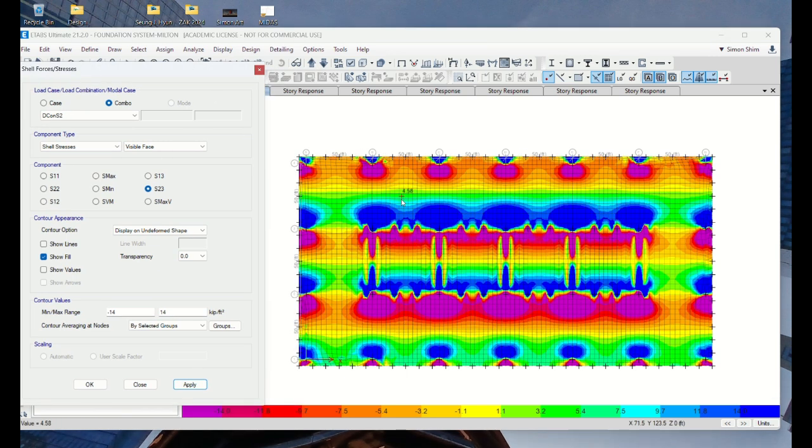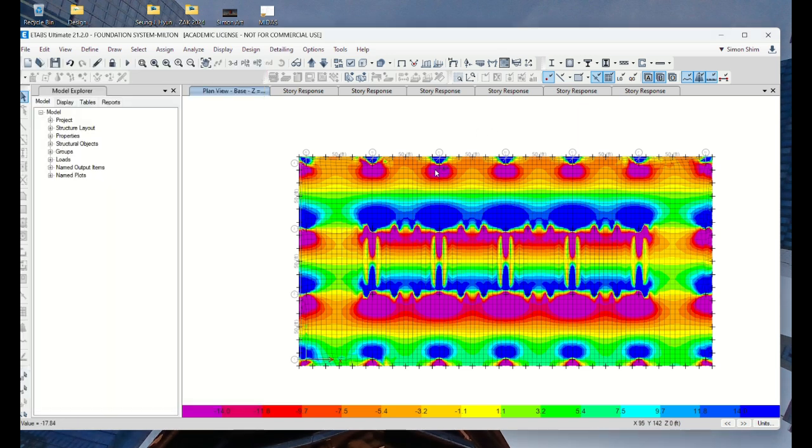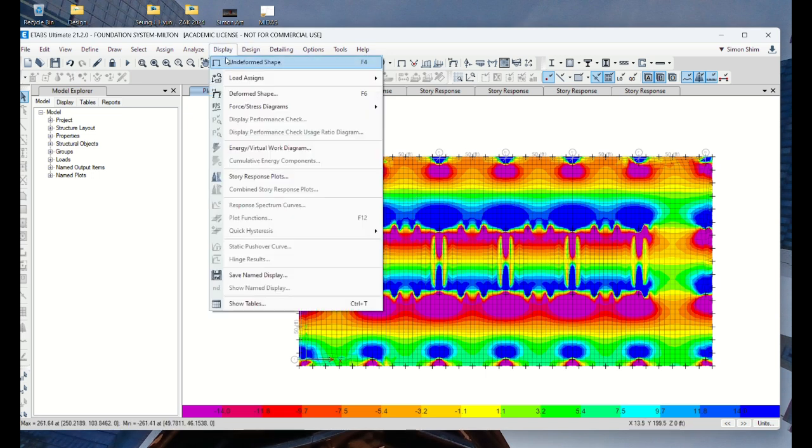Okay, you're going to see whether this ultimate shear stress is less than your concrete shear stress capacity, 0.75 times 4 times the square root of f'c. We're going to talk about that later. I'm just spot checking that the overall diagram looks reasonable, but we'll check the numbers later.